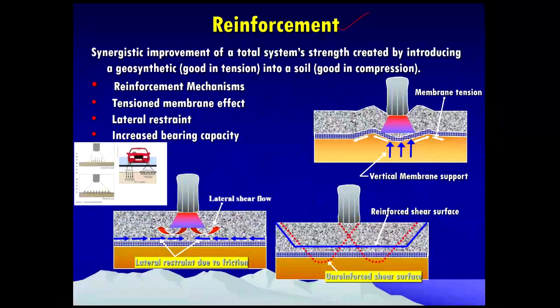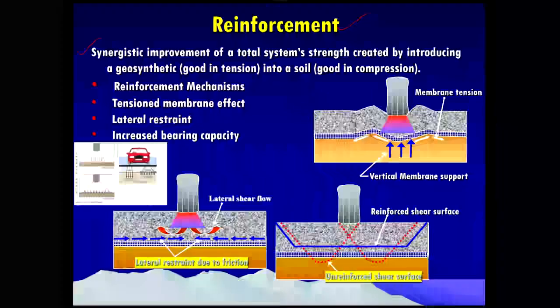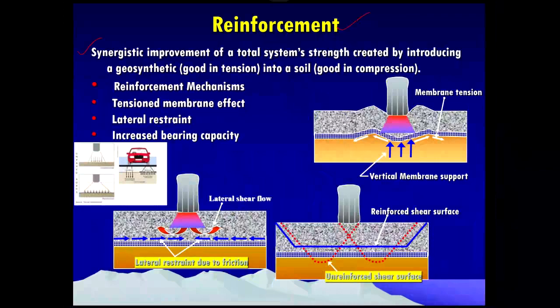You can experience that. If you remove the staple, if you remove the reinforcement, see how it collapses. If the reinforcement is there, see how stiff it is. So what I wanted to say here is that reinforcement means a synergistic improvement of the total pavement system, which is strengthened by introducing a geosynthetic in the form of a geogrid, which is good in tension, while soil is good in compression.